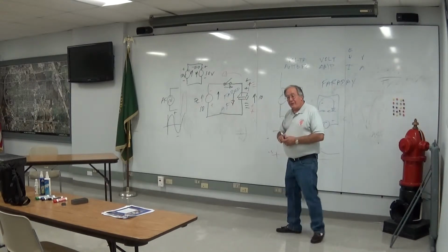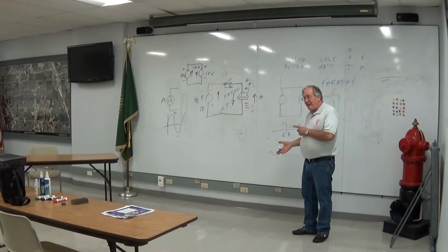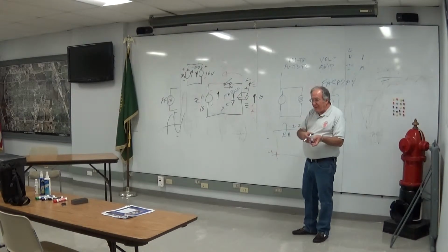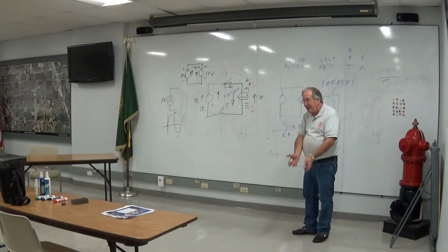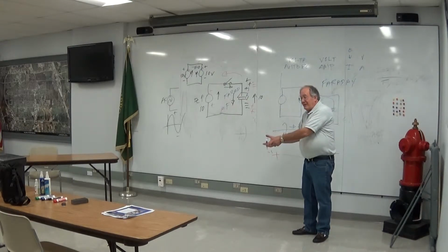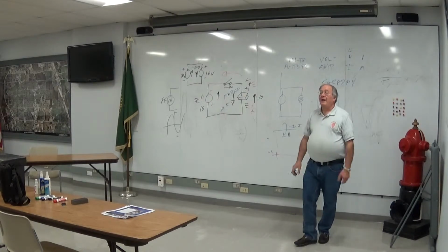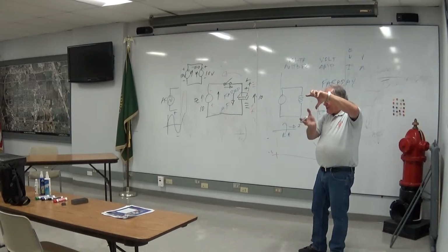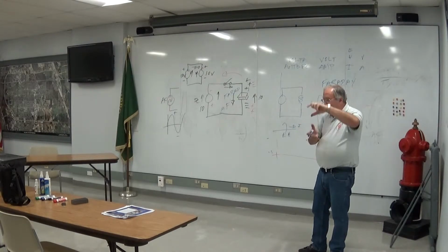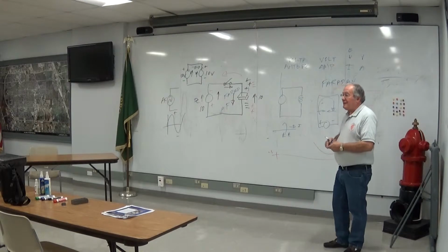And that's why the electric motor works. You put current in a coil around the motor, you get a magnetic field. The magnetic field fed to the outer winding is called the stator because it's stationary. And also to the part in the middle, we call it the armature, but we tend to call it more often the rotor because it's rotating. The magnetic field from the stator and the magnetic field from the rotor affect each other and they make the shaft turn. And that's how a motor works.